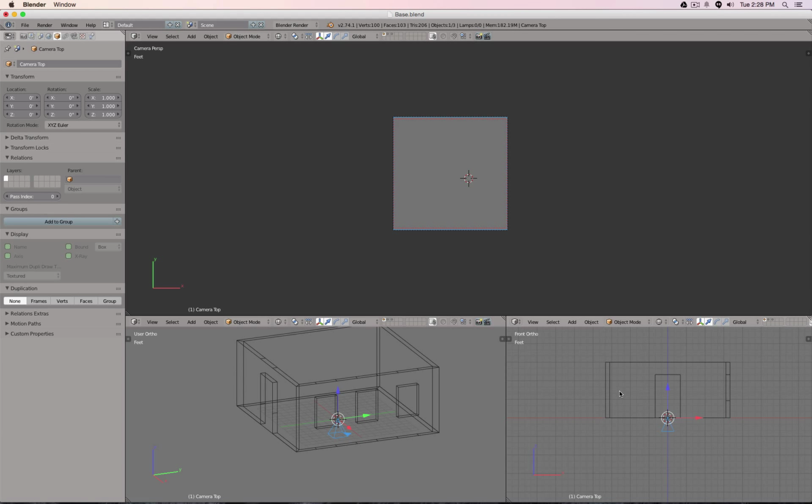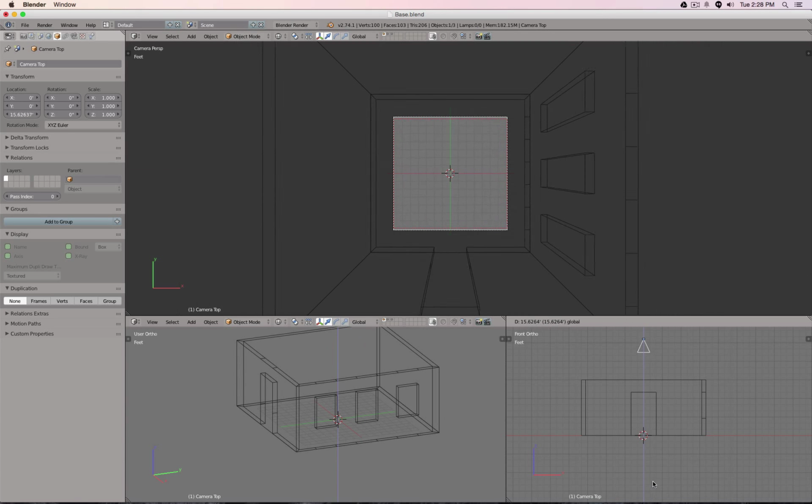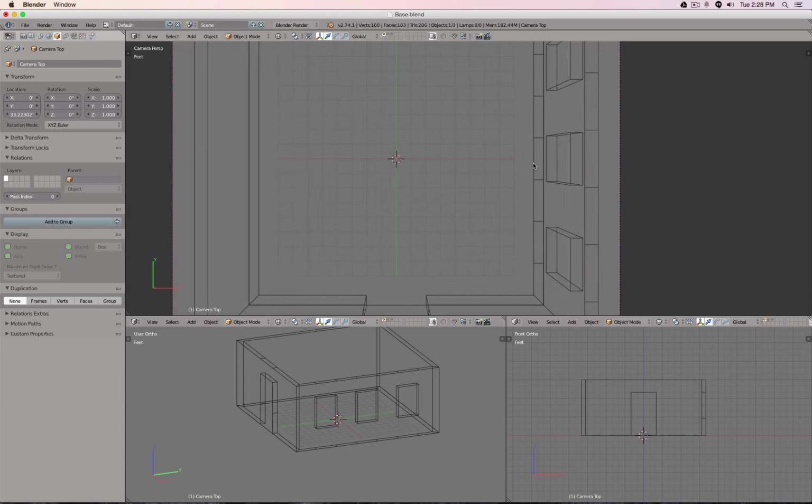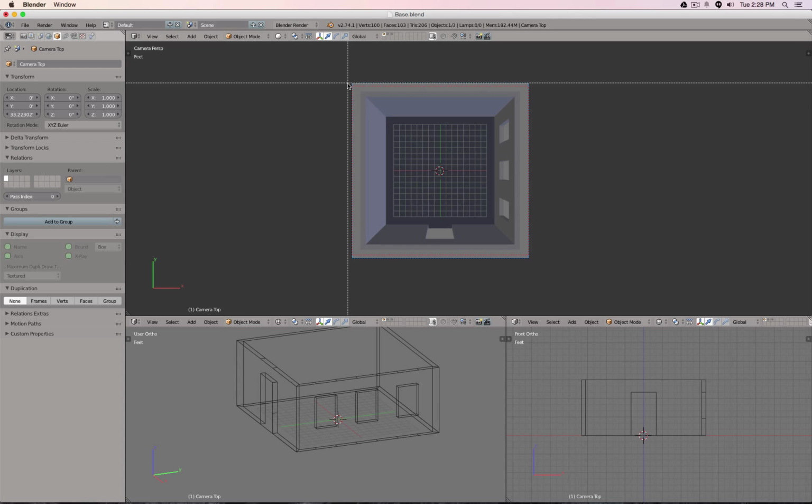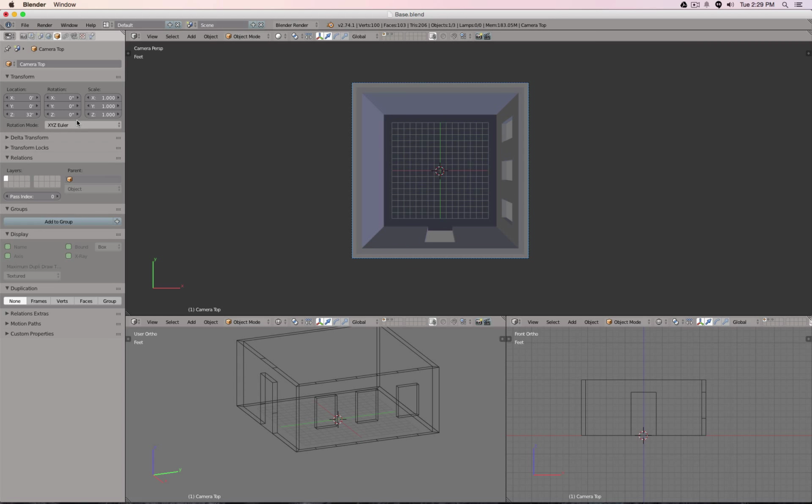And the main reason is pressing 1 to enter front view into this view here. You see the camera is below. So I have to move the camera up. And there are multiple ways. I can click, never click on the white ring because then you move Z and Y or X. I can click on the blue arrow and drag it up. And take a look there. Up there we can see actually how it moves up. Perfect. See, there we see it. Okay. You also see here inside transformation, we moved actually the camera up 32 feet. And there, we can just maybe clean it up, frame it.